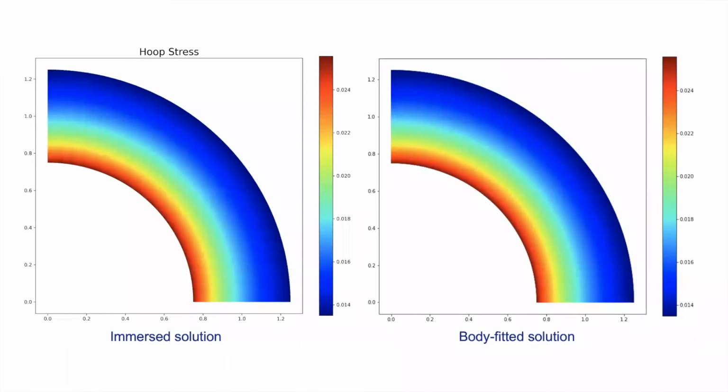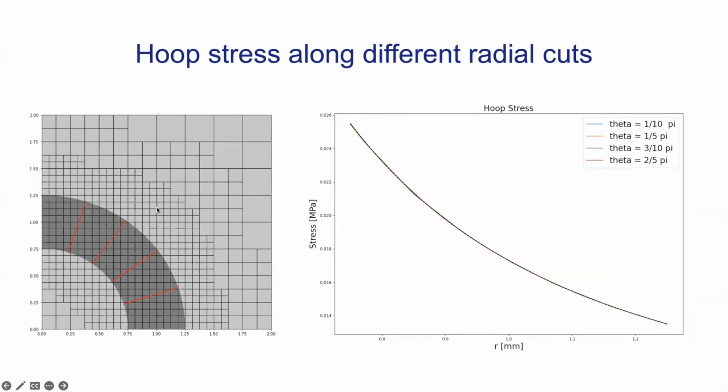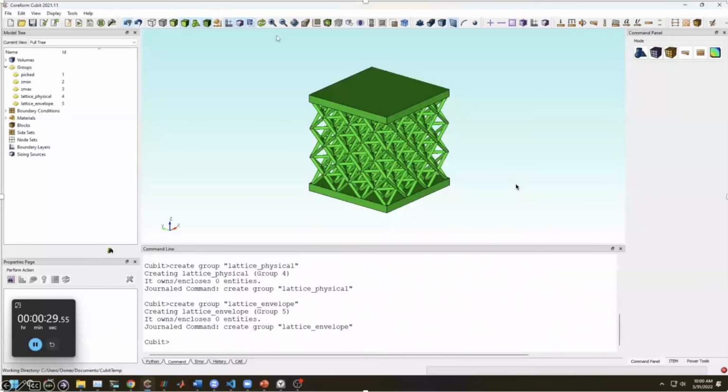And if it is, the amazing thing is, even with the immersed approach, you basically get axisymmetric response. You get the exact solution. You get the exact stresses at the wall. And this is just an indication of that. This is the hoop stress. That's the major stress, the tension there, plotted along these lines. And they're all the same, as you can see, and they're all exact.